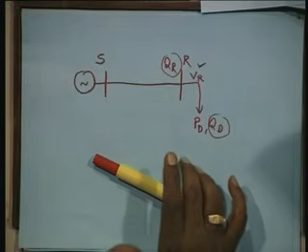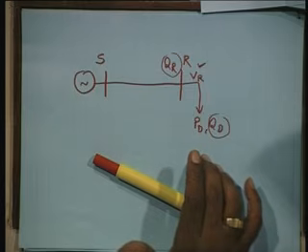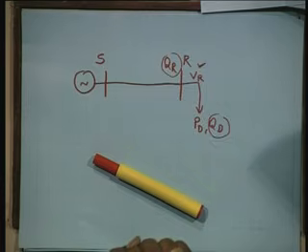Moment you start another bulb in your room or your house, you can sense dimness in the light. Have you ever seen that? Especially if you start an AC, the big load, you will feel the difference immediately. Light will be slightly dim because the extra load has come. The Q requirement has gone up, and if you don't have that much Q, the only way nature adjusts itself is that the voltage sags.